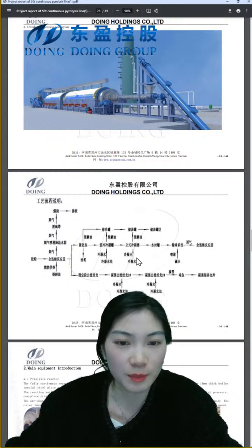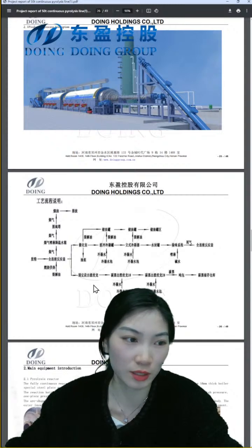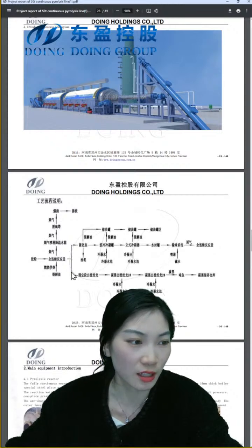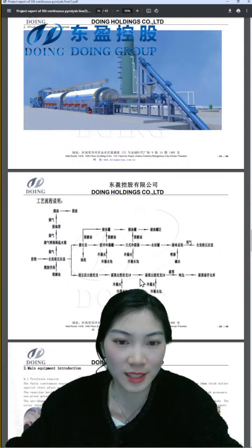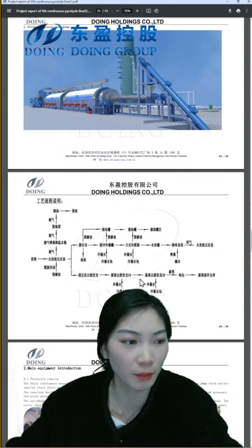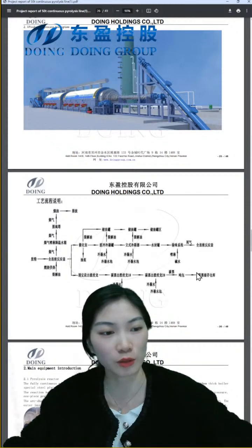At the same time, after the carbon black is discharged, it goes into the discharge auger. Firstly it flows into the fixed discharging auger. Then step 1, step 2, step 3, 3 augers. Outside is a water jacket to cool down the carbon black. After the carbon black reaches about 80 degrees, we can package it directly with a ton bag. Then just store it in your warehouse.